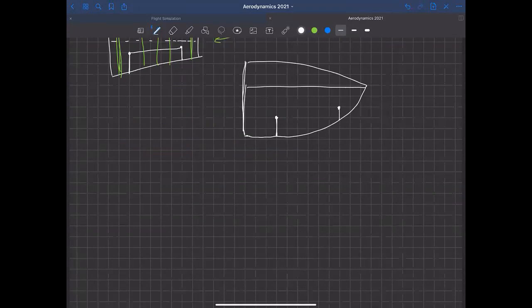Now, if we just linearly interpolate the CF over C, we're going to end up with an aileron distribution that looks something like that. But that's not really practical, because in order for this aileron to rotate, it's got to have a straight hinge line. So what we really want to know is what's the CF over C at every location that would make this a straight hinge line so that the aileron actually could rotate. Does that make sense? And to do that, we can't just use linear interpolation between these two CF over C values. We've got to do something a little bit more sophisticated.